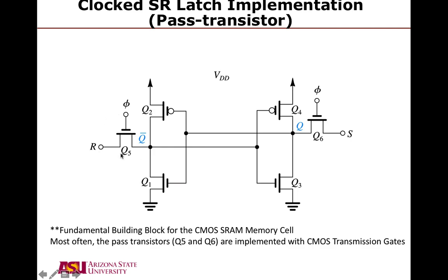And I think when you see some of the system level implementations that Micron will talk to you about, you will see that these are NMOS only pass transistors. Okay, so again, the circuits have evolved. The clocked SR latch has evolved over time to become this. Many designers, a lot of time, a lot of money to get a system like this. This is not trivial. This is not obvious.